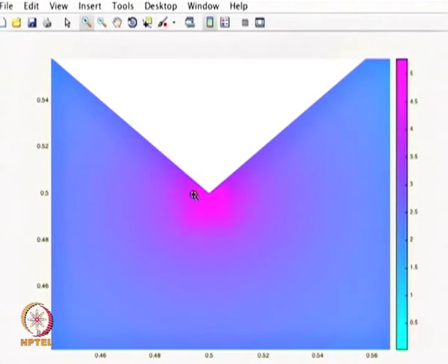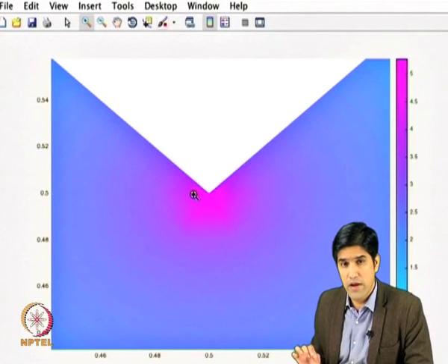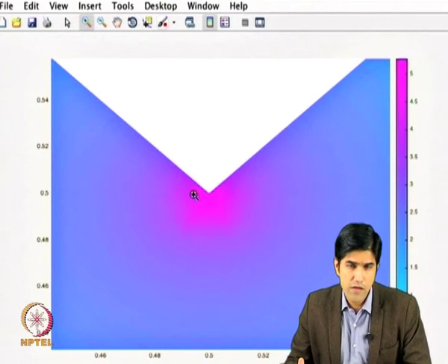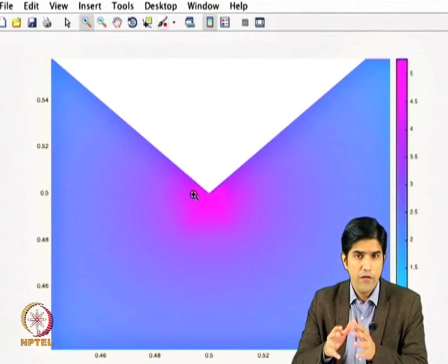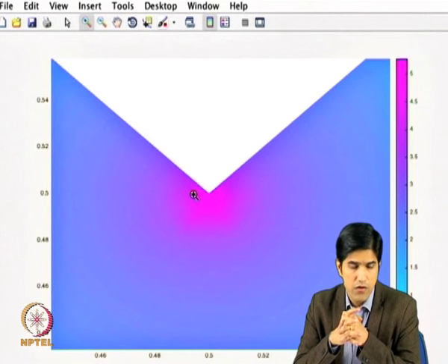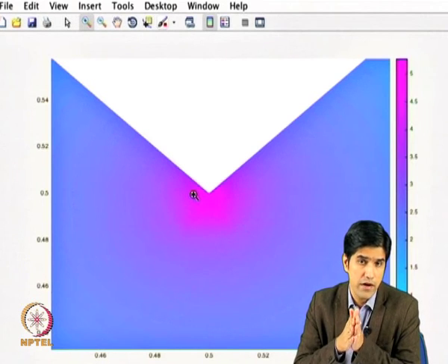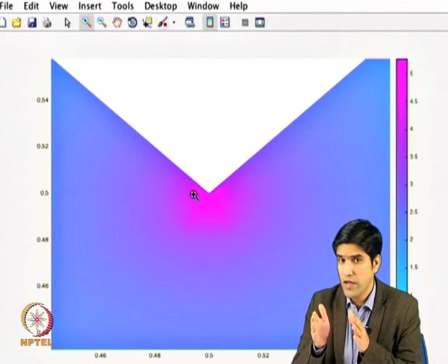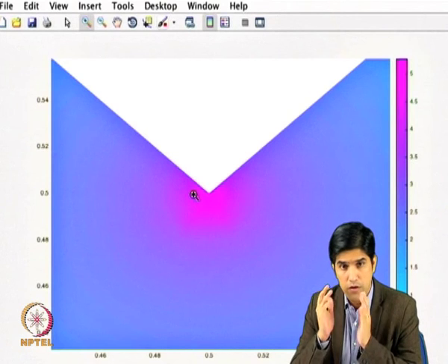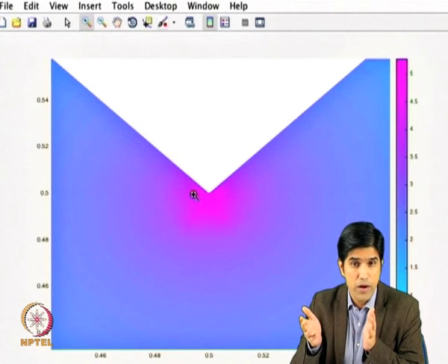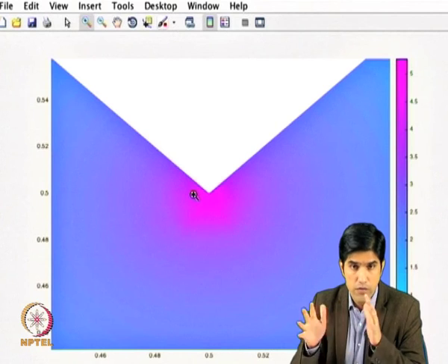So what will happen is, if you go even finer, the discretization will create a very high value, which is counterintuitive. So this is a problem that we wanted to showcase, where we actually win in terms of increasing the discretization, making the grid finer or making the grid coarser. In some cases we win, in some cases we don't win, and this is counterintuitive. People don't really know this until they simulate it, and they think the program is wrong or the code is running wrong. No, everything is okay.